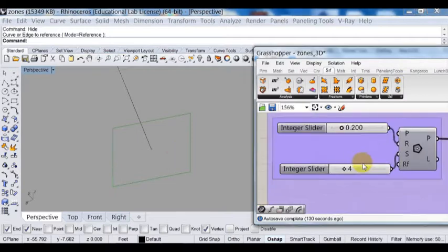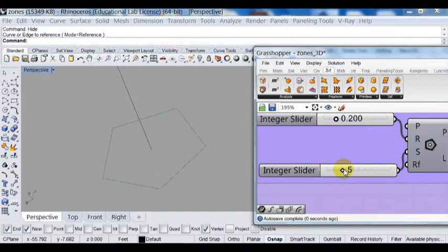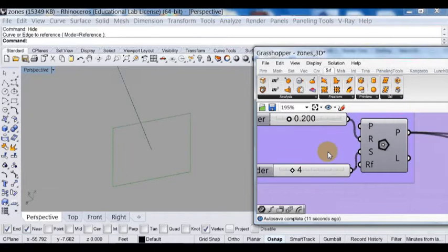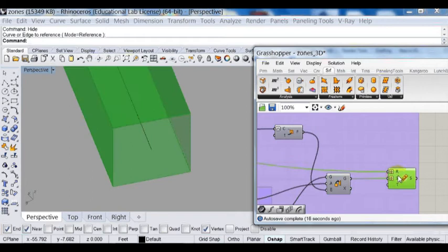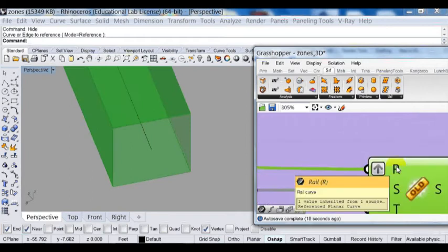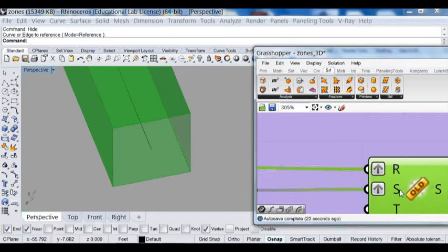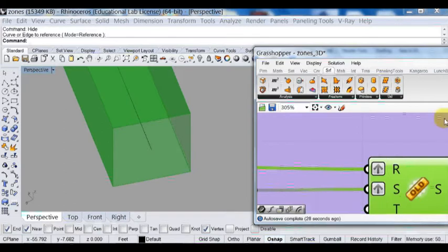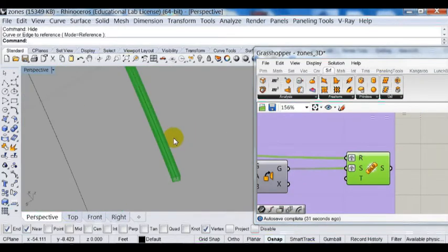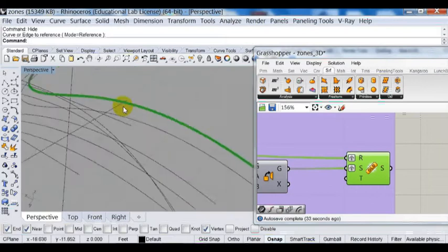If you want to test, I can change the square to a hexagon. I can change to a circle. It's pretty flexible. You can control the profile, or a triangle. So I will keep it as a 4-sided rectangle. And then at the end, I will do a sweep. To sweep, you need to input a rail, which is a curve, the path. And then the section will be the square. So that's how you create a sweep. So that's how you do one single line.